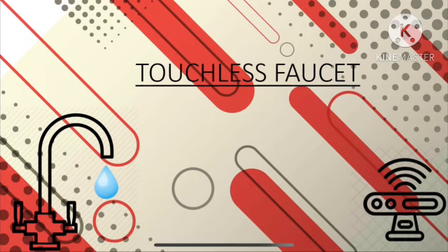This can be minimized by using optical filtering, modulation methods, and differential sensing to identify the desired infrared signal from the background light. Another issue is signal attenuation, which occurs when an infrared signal weakens over distance or due to barriers, making precise object detection difficult. Signal amplification and adaptive thresholding methods can help keep the signal strong and reliable.